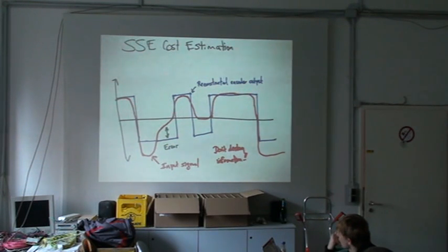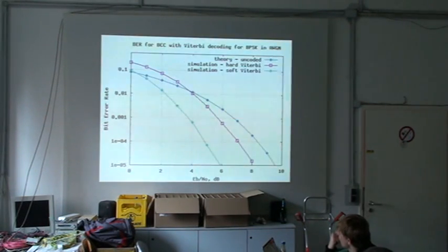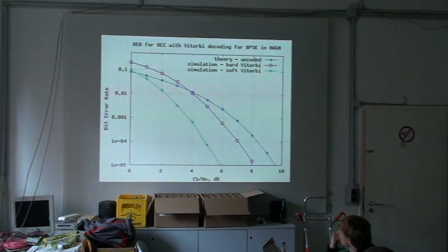So you're not going to flip bits on the decoding side. You're going to invert the sense of these soft symbol estimates. And you gain a lot by doing soft decoding. You gain about a 2 decibel improvement by doing soft decoding. And 2 decibels, in terms of effect on range and performance, is a lot.